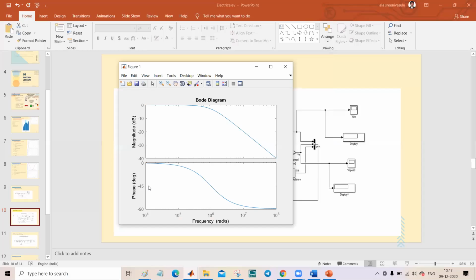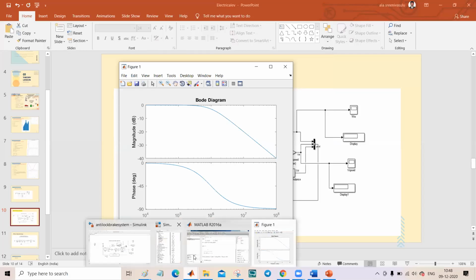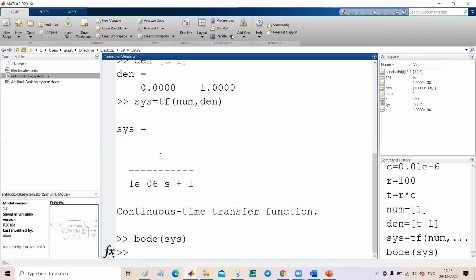First order transfer function. Now in control systems you also have the second order system here: omega n squared by s squared plus 2 zeta omega n s plus omega n squared, right? So if you need to draw that diagram and you know the parameter values, what is omega n, 2 zeta omega n s, all these things you can develop, and you can derive the transfer function from like this only.